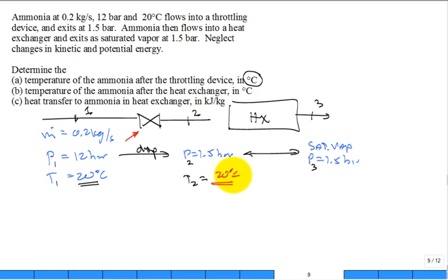And this is the miracle of refrigeration. It's incredible. You describe the fluid coming into state 1. It's basically subcooled liquid. It's a liquid state. It could be saturated liquid, but if you look up ammonia, my guess is it's subcooled liquid. Let's take a look. What is the saturation temperature, Tsat, for ammonia at 12 bar? The first one to get there, tell me what table you're in.